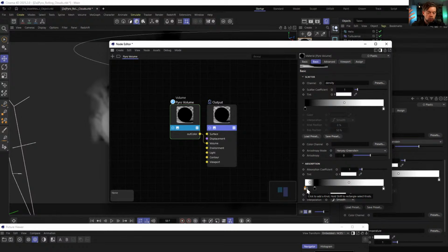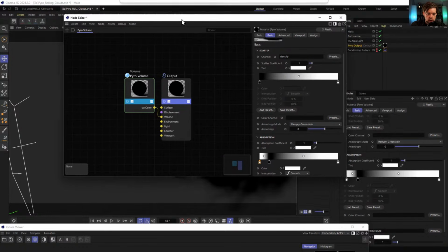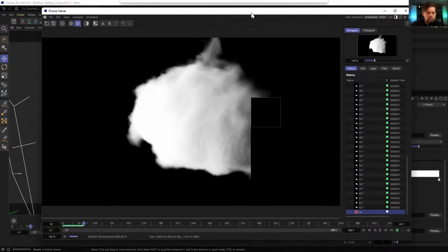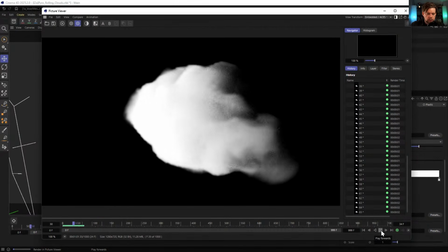So the goal there would be, we've got this giant voxel grid of noise that's going to start drifting around. When it's at its most dense, meaning looking the most like little cubes, we don't see it. But as soon as it starts moving and drifting away, suddenly it becomes more opaque. So it's almost like it would be constantly fading in. So that potentially could do a little something for us. I'm pretty much going to stop the render here, and we'll just see if we can do a little bit of stuff with that density.